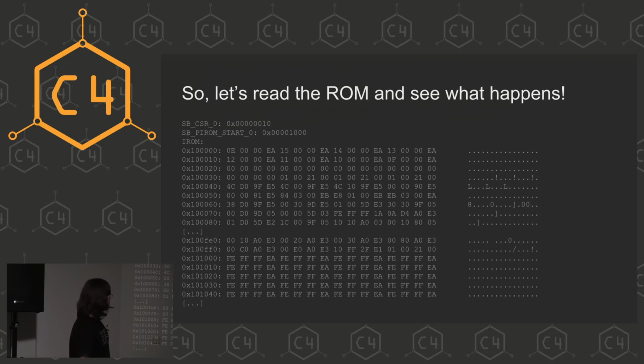At this address, this looks like code. This actually looks like ARM code. I can tell not because I'm a disassembler, but because there is a trick to ARM code. If you see a lot of E's here in this byte, and this byte, and this byte, this has something to do with how instructions are encoded on ARM. This is a good pointer that this might be ARM code. Also, if you disassemble this, you can see that this code actually makes sense.